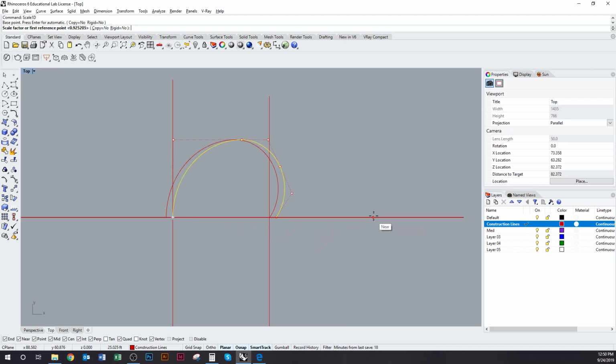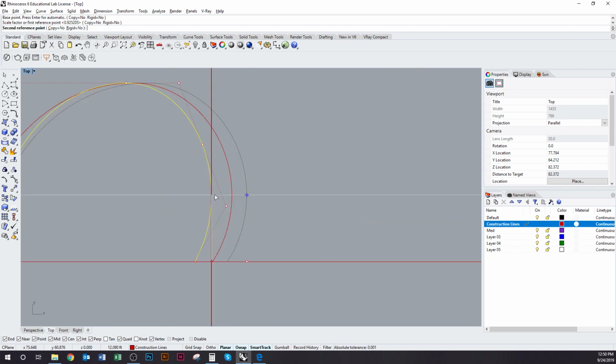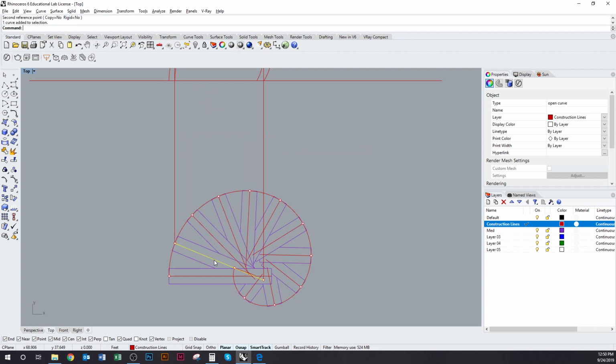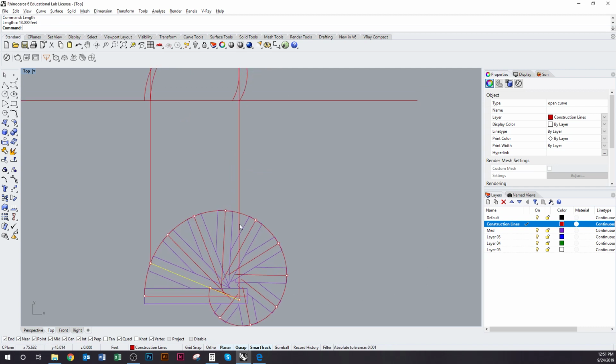The other way you can do this, by the way, is if you draw straight out and hit Tab on the keyboard. Again, that constrains your cursor to one direction. Now it's easier, we can just snap to that quad and bring it back. And I'm going to try and follow the same rule here. So the length of this one is 13. 13 times 2/3, 8.58.